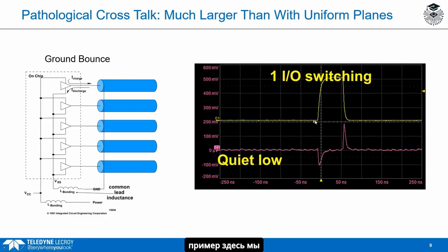And here's the example. Here, we're measuring one of these I/O that are switching. All 4 of them are switching. We're measuring one of them, and here's the voltage on the low side. And we see that when we get current turning on, for example, we get a voltage over here that's lower than the local voltage over here. And when the current changes direction and heads back this way, we're going to get this side a higher voltage than this side. This is switching noise, only arising when the I/O changes state, when the currents are changing.